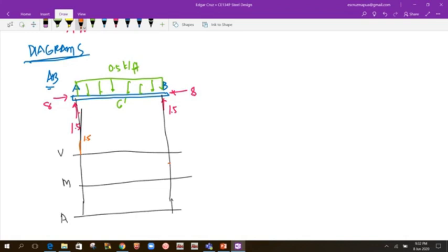Since the uniform load is degree 0, the shear would be first degree. Since both are 1.5, one positive and one negative, this point of intersection would be half of 6, at 3 feet. Then you have 1.5 going up, so negative 1.5 plus 1.5 closes the diagram. It involves this area of the triangle over here, and an area of the triangle here as well.